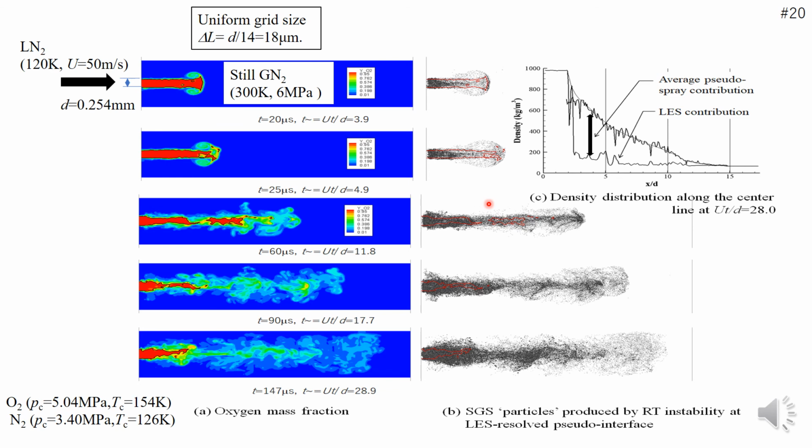The diffusion coefficient takes a small value at high pressure, therefore the binary mixing is dominated by a large area increase in the contact surface of the two species. In the present simulation, the contact surface consists of the pseudo-interface and the sum of Sds dense fluid thread surfaces. The meandering of the dense fluid jet generates large vortices and reduces the intact lengths significantly compared to the subcritical case.